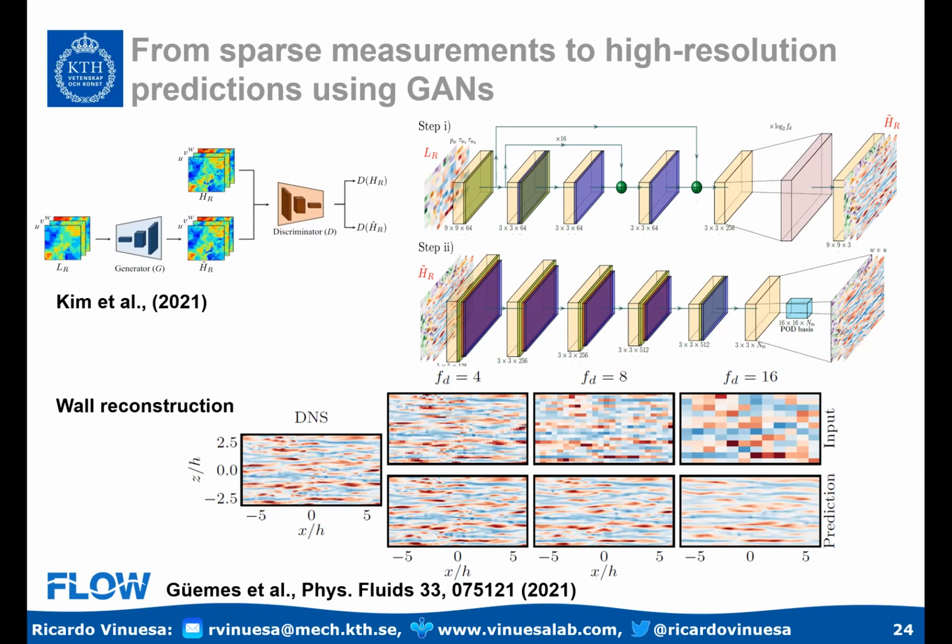And then on the second row, I'm showing you the predictions of the wall shear stress that we want to compare with this panel over here. Now, keep in mind, with this one that you can see, you are losing completely the coherence in the data, no? Because it's point measurements where you don't really reproduce the structures, you're really reconstructing a lot. But it turns out that the predictions are always quite realistic. In fact, in this case, the agreement is pretty good.